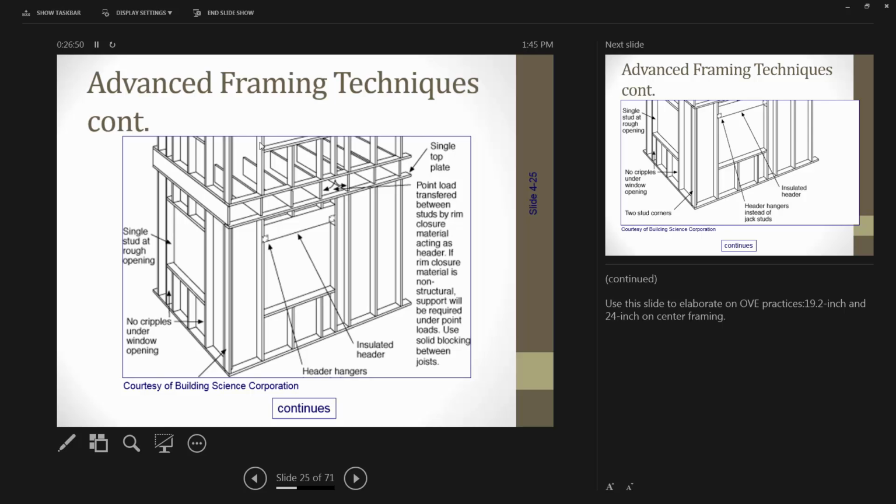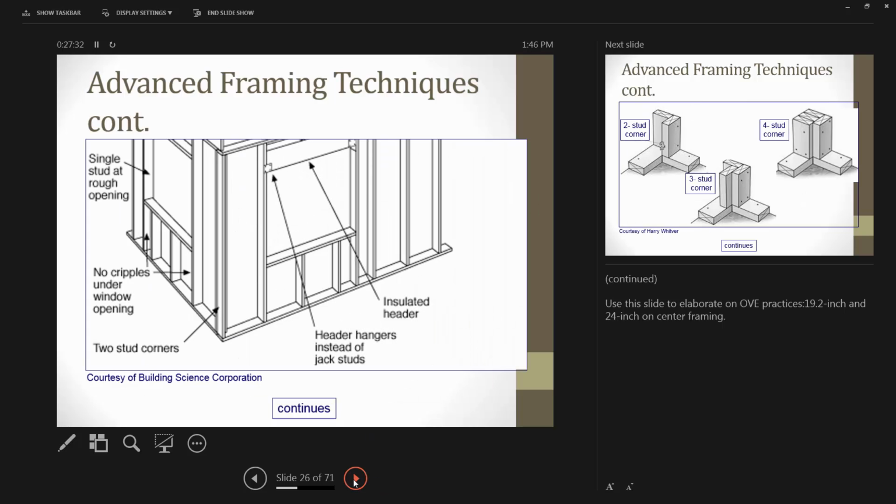If you have your floor joists and your studs not lined up and you've got to add bearing in there, you're just adding more wood into the wall. And the more wood you add into the wall, the less insulation you have in there. So next week we're going to work on doing some conductive heat loss calculations. When we figure those conductive heat loss calculations, and you look at the inefficiencies of standard framing versus advanced framing technique, usually you can see about a 10 to 15% increase by using advanced framing techniques and reducing the amount of solid sawn lumber that's in the wall.